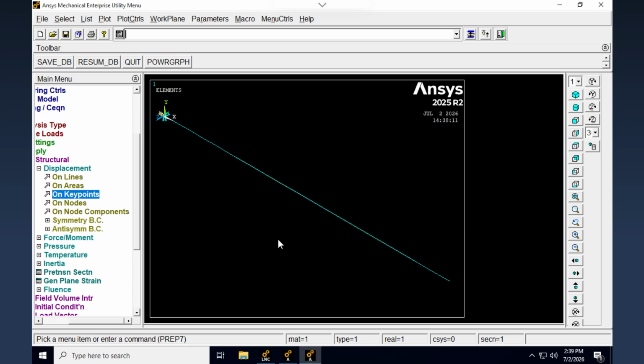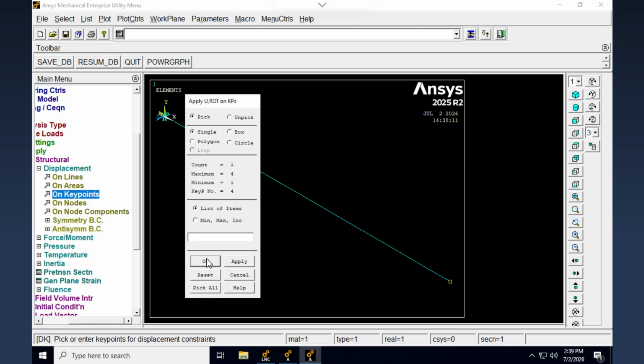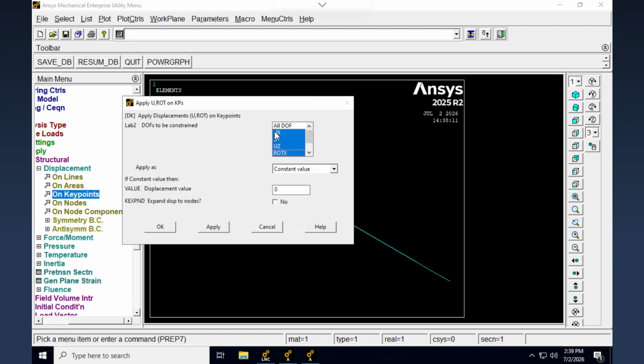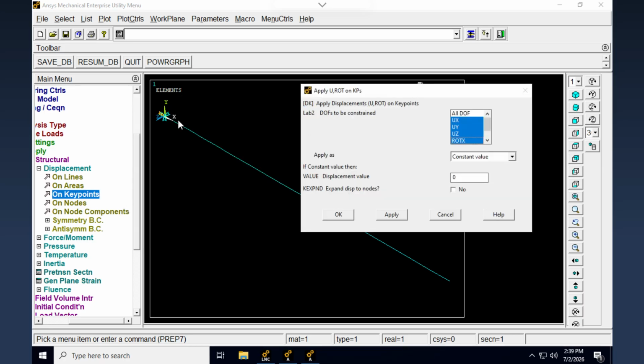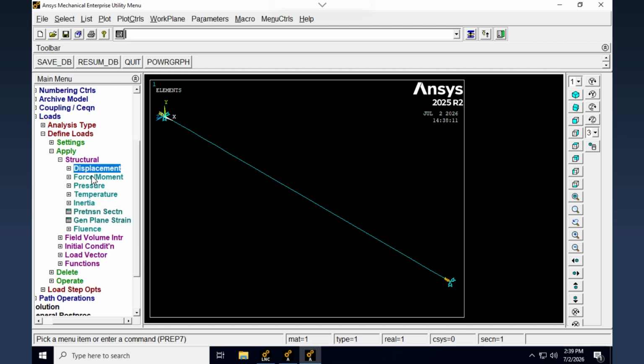Alright, so this is it. And the right one, usually with bearings, one side is fixed and the other side is floating. So on that right side, I can say X has freedom in the X direction. I'm not gonna zero that one. And then Y and Z, I'm gonna fix those. And for rotation, you can say rotation about X is 0, but the other ones I let be free. Okay, so this is our bearings.